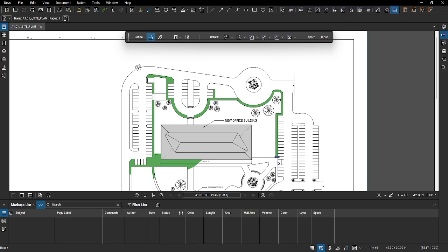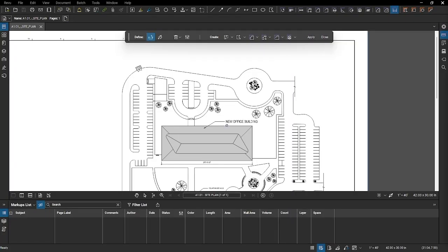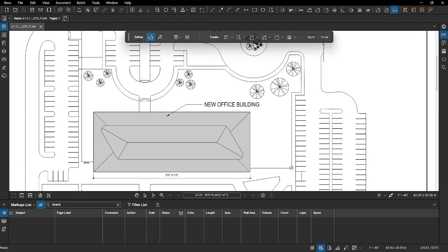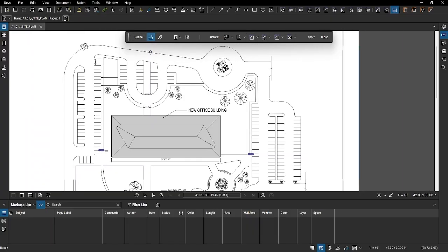If you're unhappy with your selection, you can clear it. Click on the trash can icon to see your options to clear your boundaries, clear your fills, or all of it. Select Clear All to start over again. This time, place the boundary exactly where you want it to align with the bottom edge of the walkway for accurate measurements. Place the fills in the walkway and the curbs above the building.